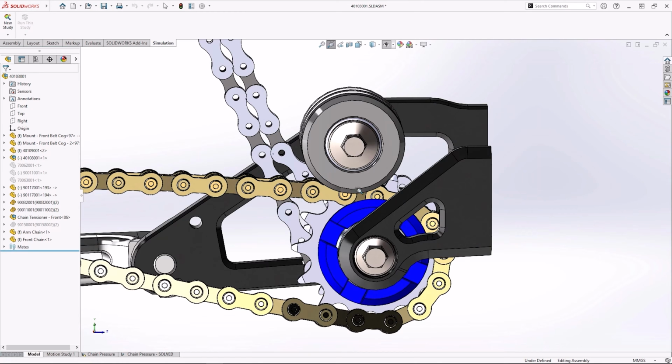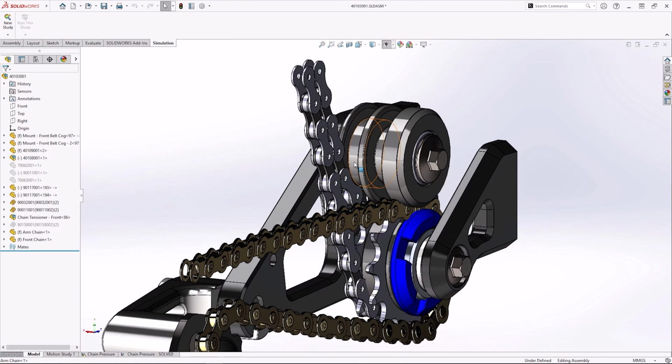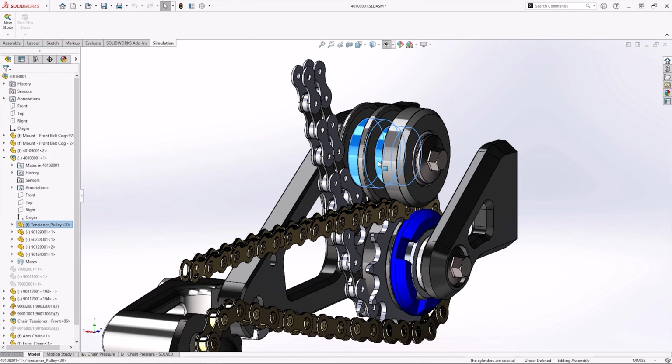This chain assembly is responsible for transferring power from the rider's arms to the assistive power unit and rear wheel of the Bowhead RX. You can see there are two chains running through the tensioner. Next to the chain is the chain roller guide. The roller guide is responsible for keeping both chains on the transfer cogs, ensuring that the chain doesn't slip off under power.